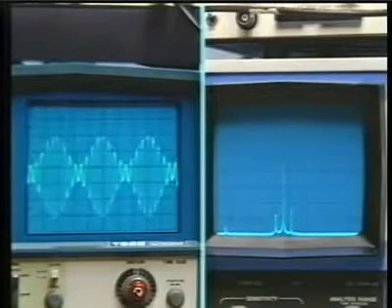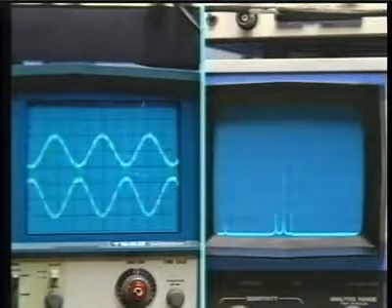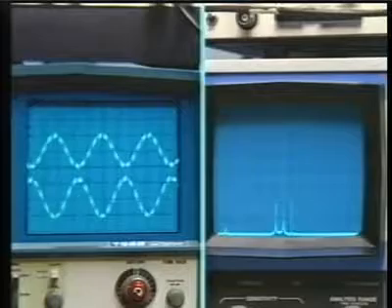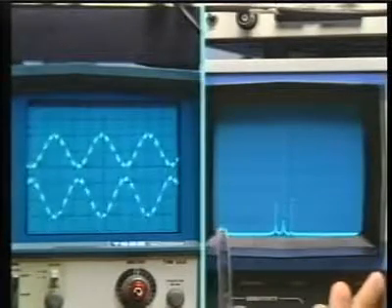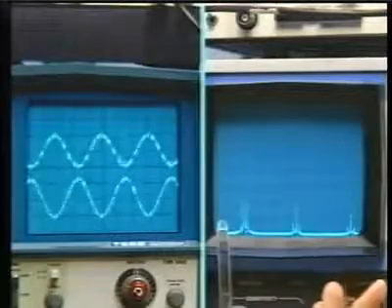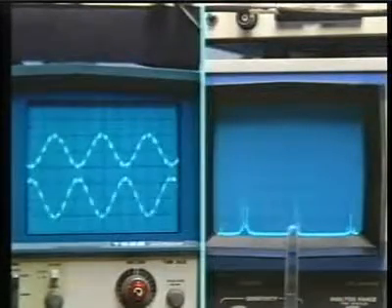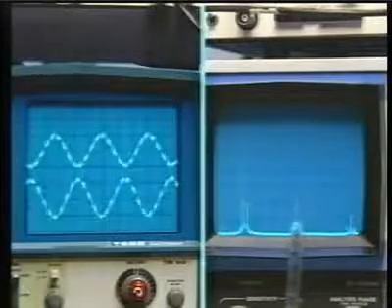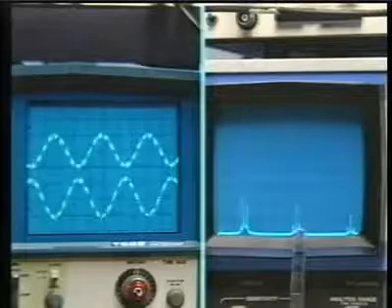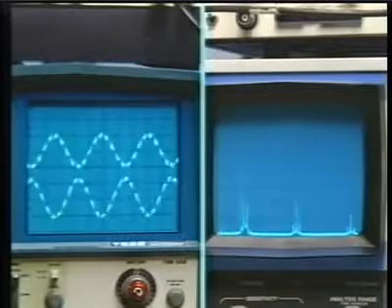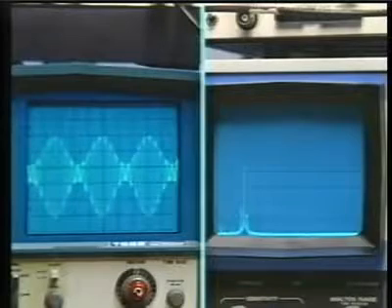And let me change the carrier signal from a sine wave to a square wave. Now, you haven't seen any change on this particular display, but let me change the frequency scale. And what you see now is the modulating signal showing up around harmonics associated with the carrier. And those harmonics will go away when we go back to a sinusoidal carrier.